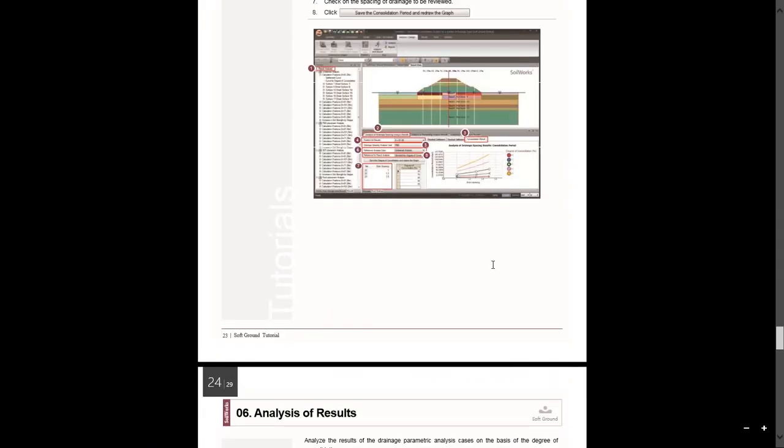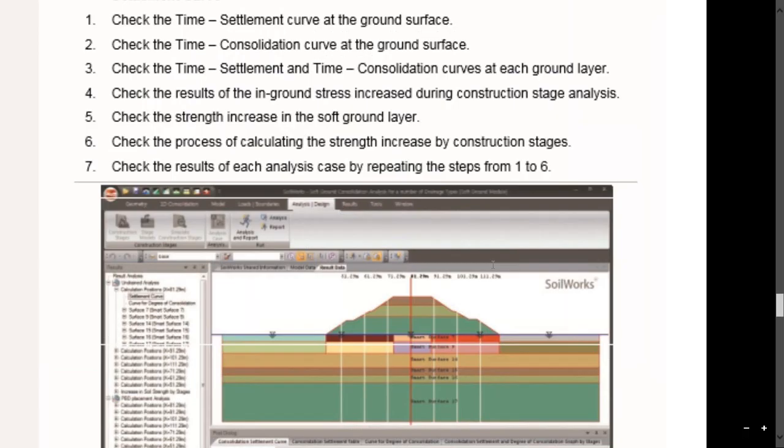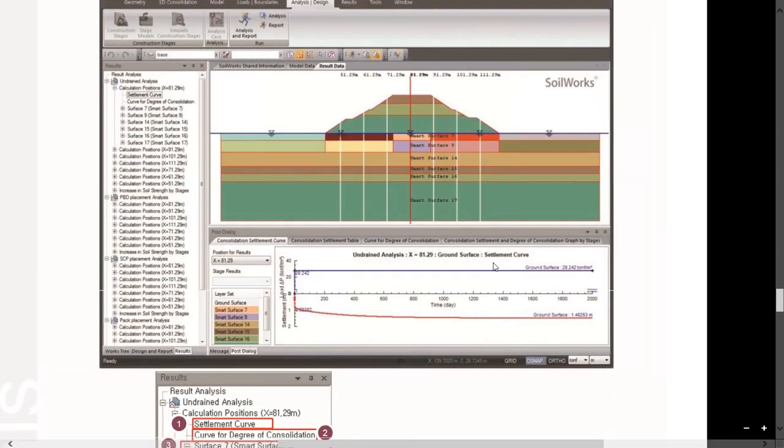with your current project. Just keep in mind that one of the main advantages of the 1D consolidation method is that you can analyze how your embankment or your project site settles over a much longer period of time. So in addition to the immediate settlement, you'll also have a secondary settlement, which shows over a number of years or months the additional settlement that will take place.